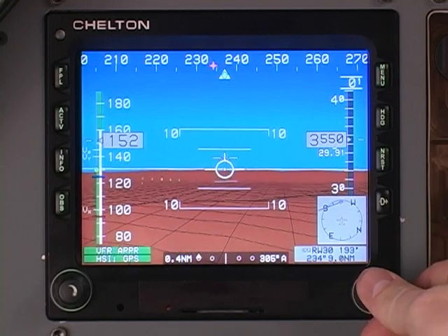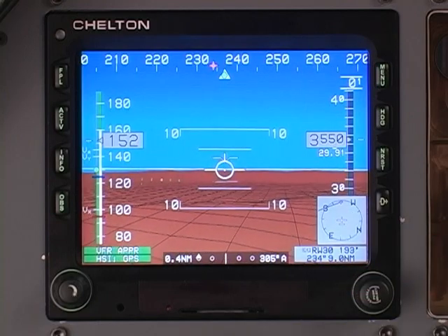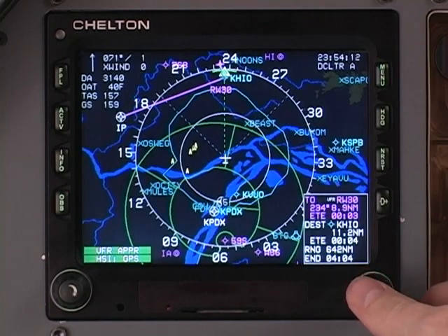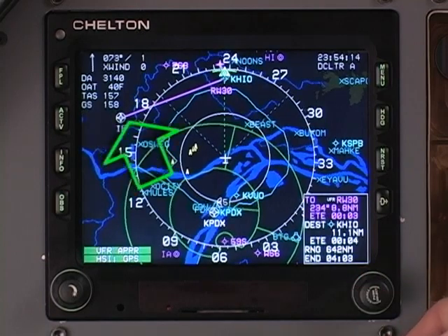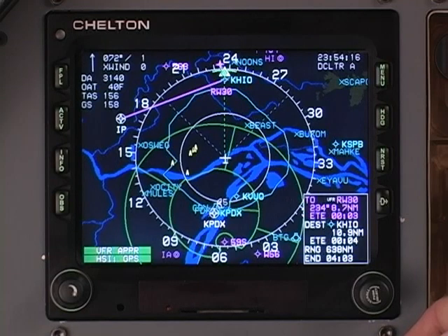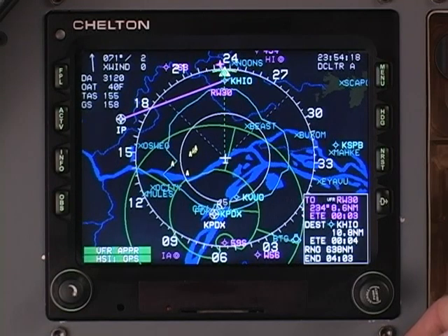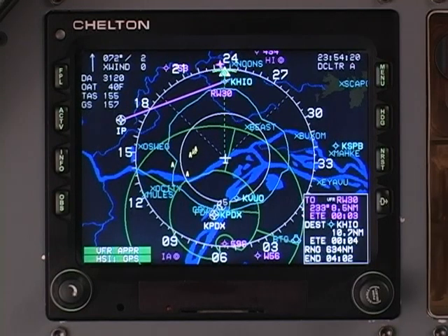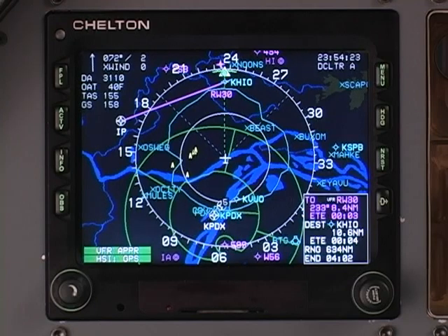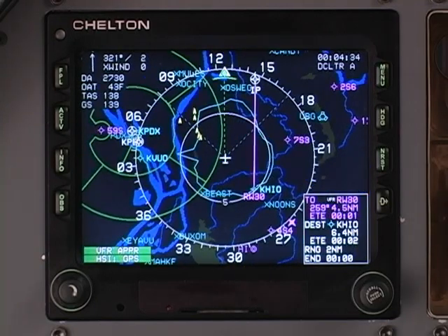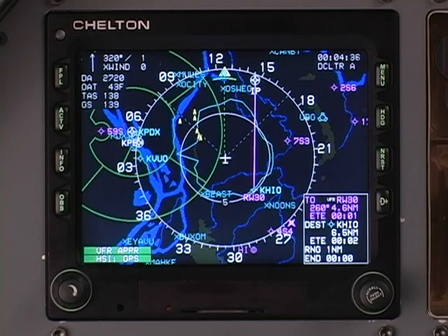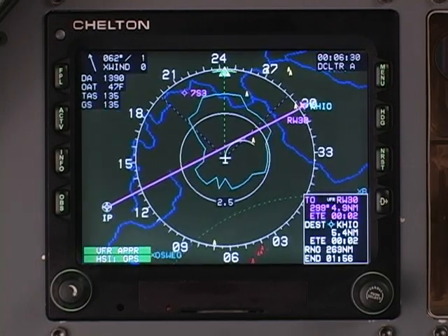The course in the map and the Skyway will depict an extended final approach course from an initial point labeled IP to the touchdown zone. Since the EFIS doesn't know where you intend to intercept the final approach course, the IP is preceded by a discontinuity in the course line. Use the lubber line and projected path to fly a nice square pattern and smoothly intercept the final.